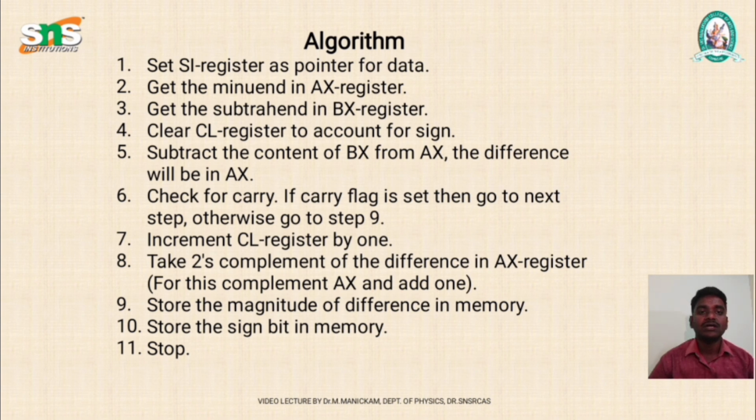That stored address is 1104. Then the carry will be stored in 1106. Then store the sign bit in memory; 1106 is where the sign bit will be stored. Then the last step is stop, the end of the program. So this is the step by step guidance for the 16-bit subtraction program.